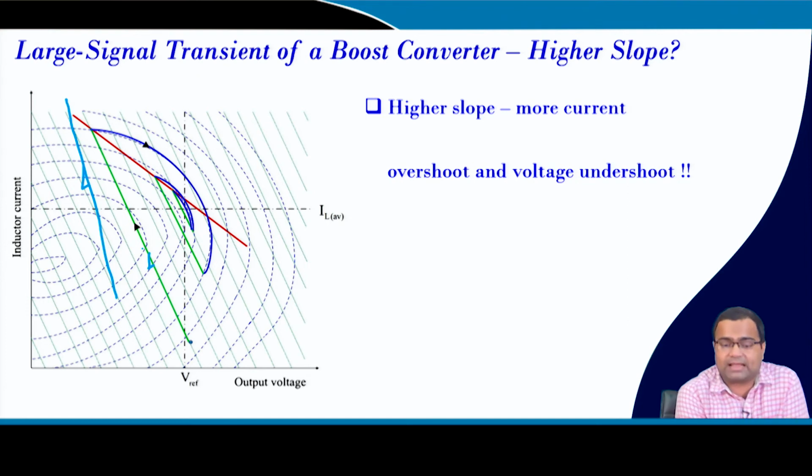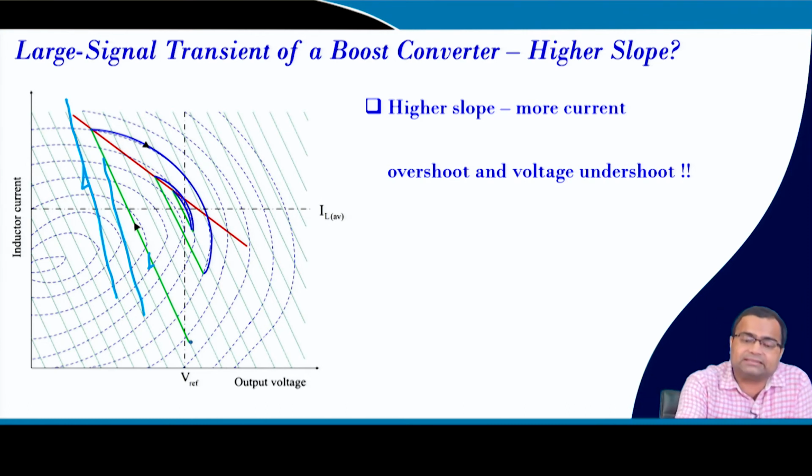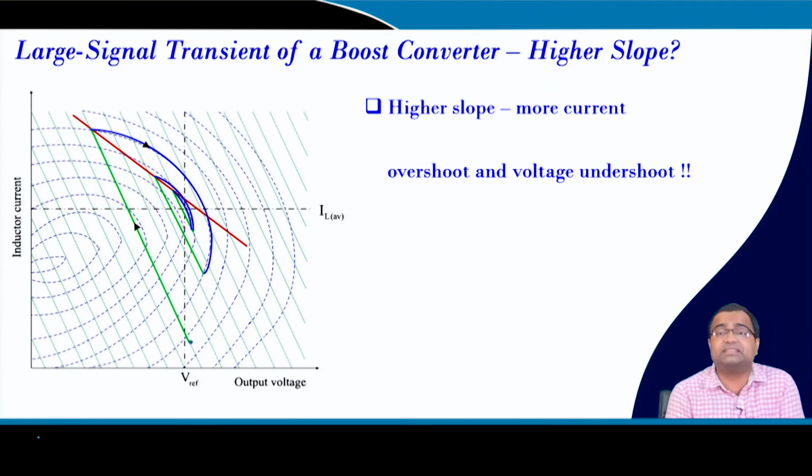As a result, suppose this is your switching surface, you are actually reversing the switching logic, and if I take this trajectory here, it is going away from here, right. This is the on state trajectory, and this side also the trajectory is going away. That means, this is a scenario where we have a rejective region.